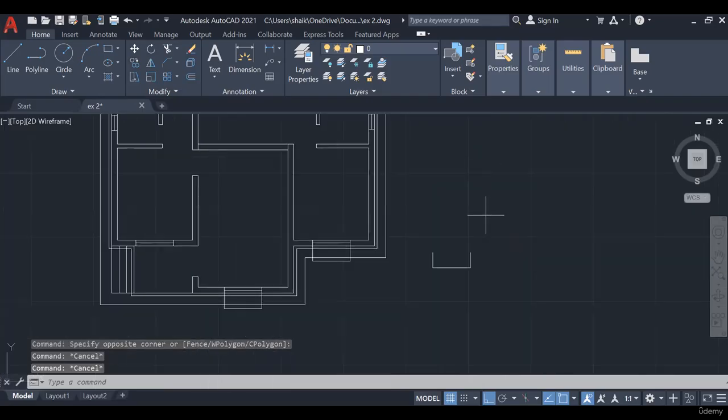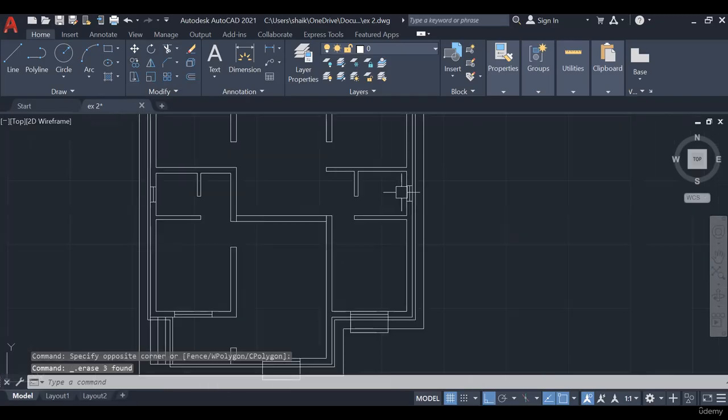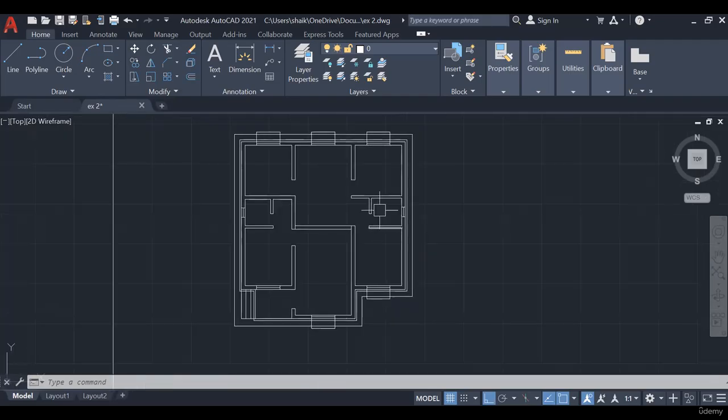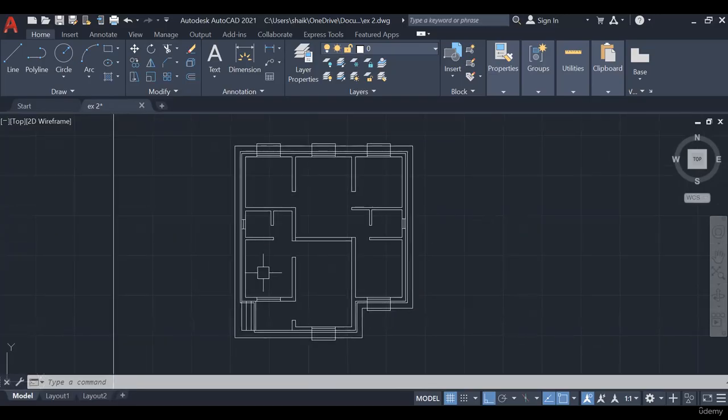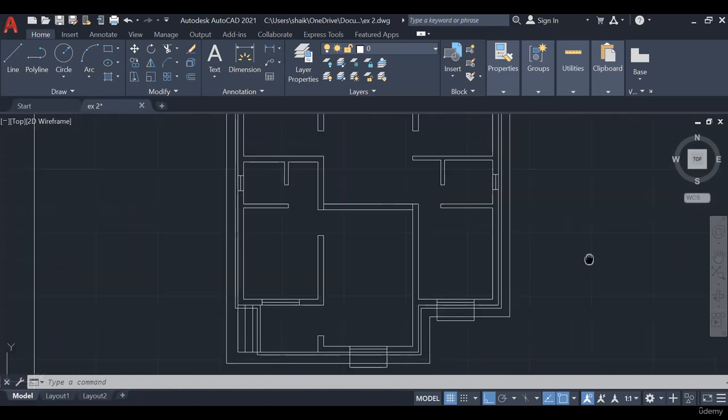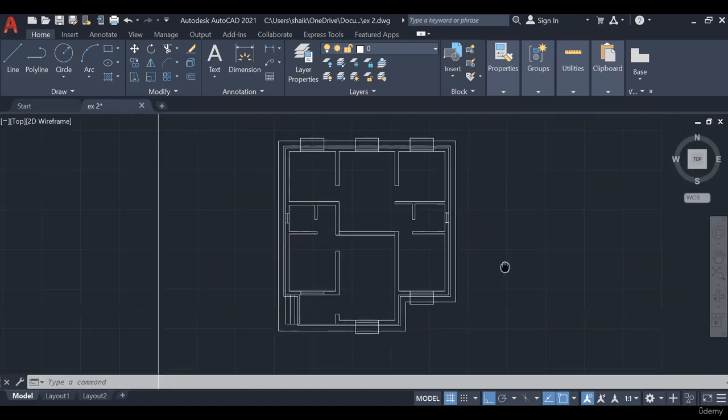And for ventilators we are not providing the Chhajja. Sometimes it is provided, but sometimes it is not. Why is it not provided? Because their size is very small and the depth is also very small. That's why we are not providing it. So we have provided the plinth, the Chhajja plinth projection, the slab projection, and the Chhajja projection. Correct?